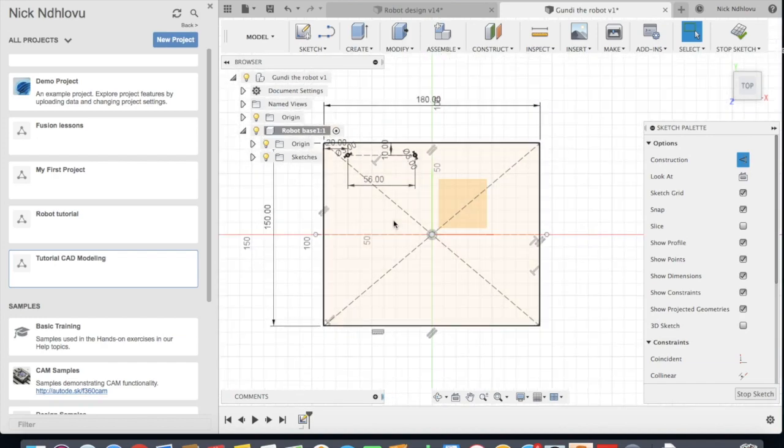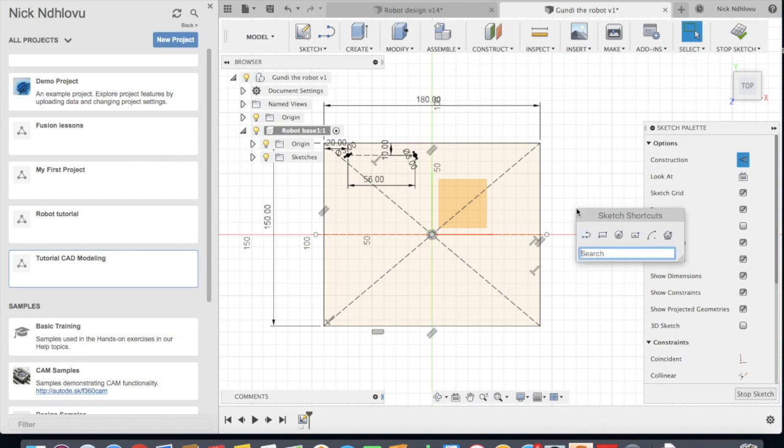Then now I'm gonna go to my toolbox again, type in S, and then now I'm gonna look for the mirror feature. I'm gonna type in mirror. As the name suggests, it just mirrors features or components on the other side of a plane or the other side of the line. So I'm gonna click on mirror here, the first one.